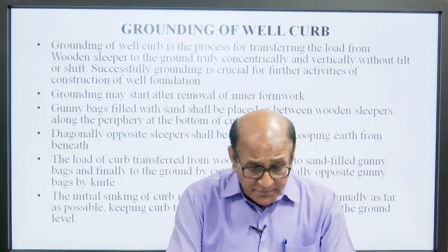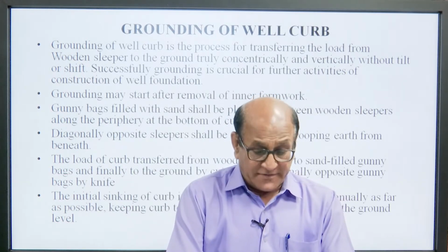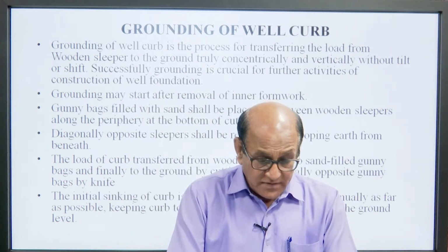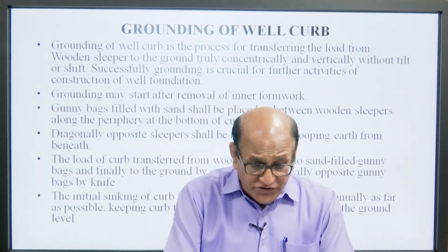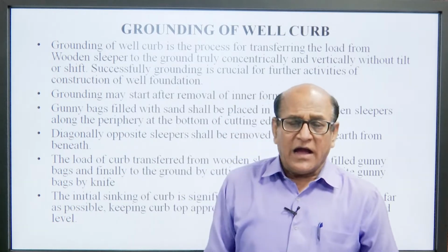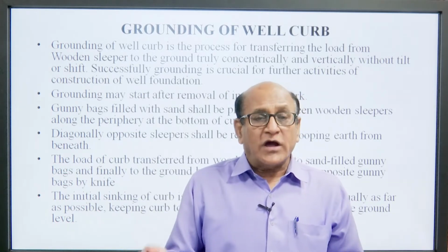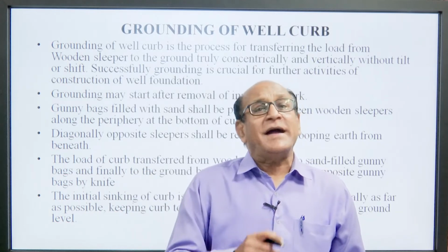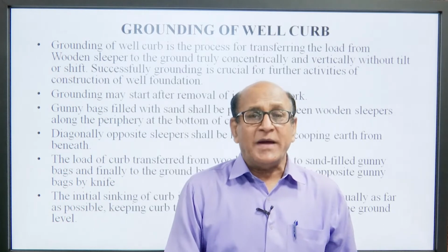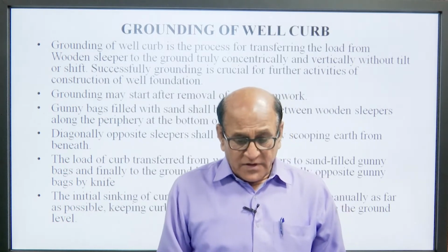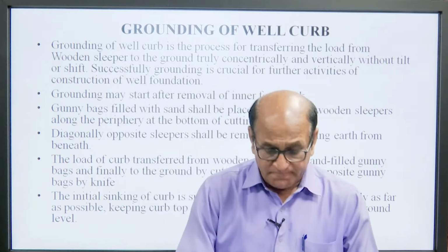The load of the curb is transferred from the wooden sleepers to the sand filled gunny bags and finally to the ground by cutting diagonally opposite gunny bags by knife. After putting the load, the gunny bags are cut by the knife so that the sand comes out from the gunny bags and our well curb will be placed on the actual ground.